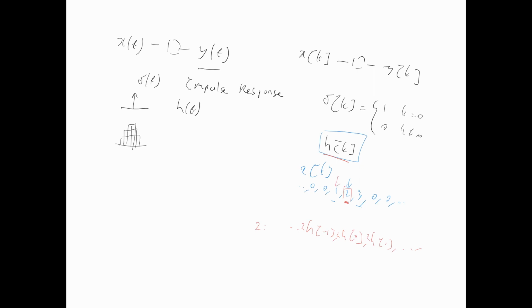For the 1, if I put a 1 into my system, ordinarily I would get out just the impulse response if that 1 had occurred at time k equals 0, but it's been shifted 1 unit to the left. So therefore my output, and I'm going to assume that my time 0 lines up with this line here, k equals 0. If I apply a 1 to the input at time k equals -1, then I'm going to get my impulse response, but shifted to the left 1 unit. So I'm going to get h0, h1, h2, ...